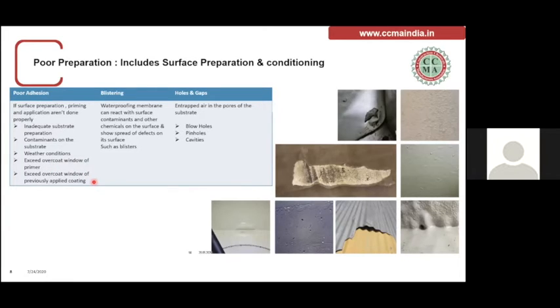So you do a hand applied polyurethane system or a hand applied polyurea first coat, and then after a specified time, you do the second coat. So that is also a problem. So the last two are more like application problems, and the first three are something which we can control by proper surface preparation.